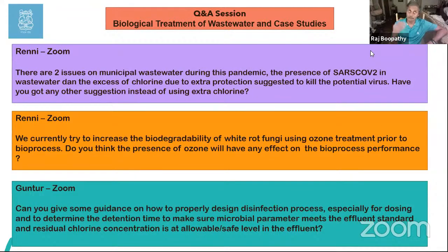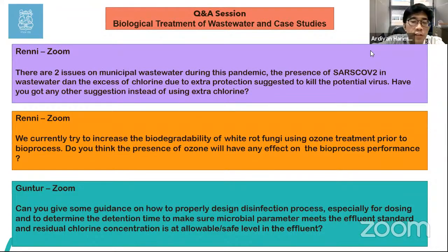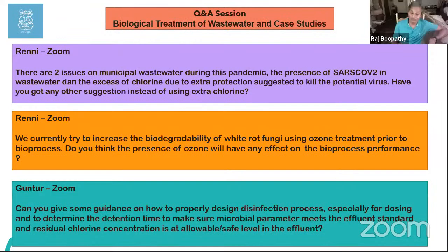What's your removal efficiency? 95% removal, 100% removal? You need to play around with the chlorine dosage. But when letting it out into a river or stream, 0.5 ppm residual chlorine seems to be okay. Whatever is left after the treatment, you don't have to worry about it affecting the natural system.